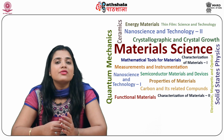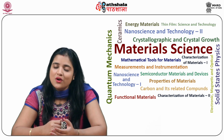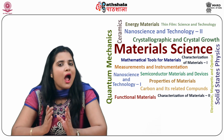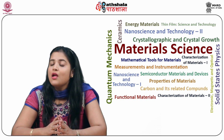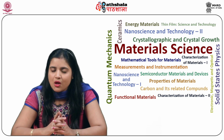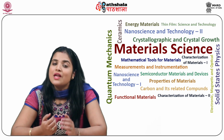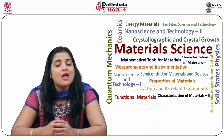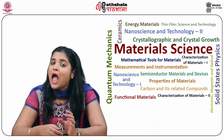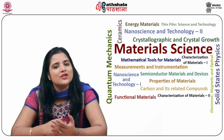Let us next take up the analog to digital converter. Analog to digital conversion involves the conversion of analog voltage into an equivalent digital signal. A number of methods are used for analog to digital conversion. However, the simplest one is the simultaneous method. It is also commonly known as flash ADC, as it has a very fast response and is thus the fastest method for converting analog into digital.